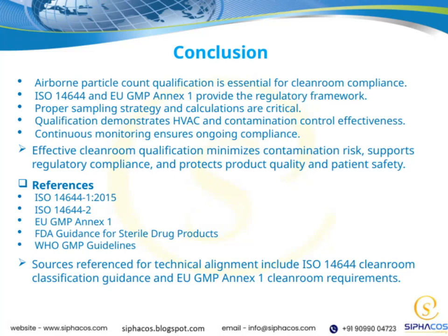In conclusion, understanding and implementing airborne particle count qualification is absolutely essential for maintaining cleanroom compliance. This process ensures that the environment consistently meets the strict standards set by regulatory bodies. As we've discussed, frameworks like ISO 14644 and EU GMP Annex 1 provide the necessary guidance and requirements to follow. It's also crucial to develop a proper sampling strategy and perform accurate calculations, as these are key to obtaining reliable data.